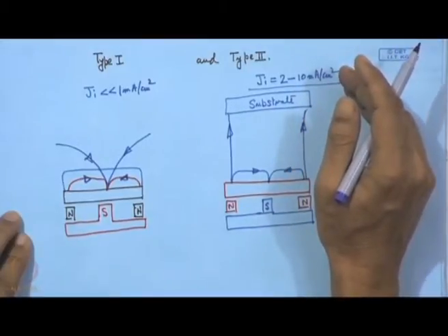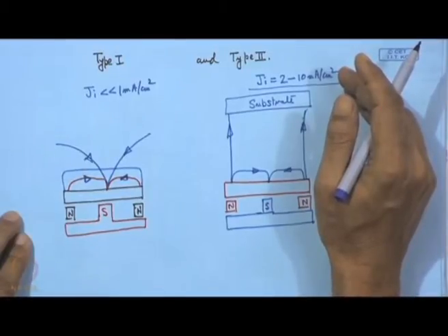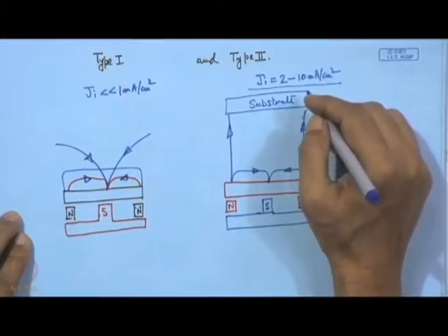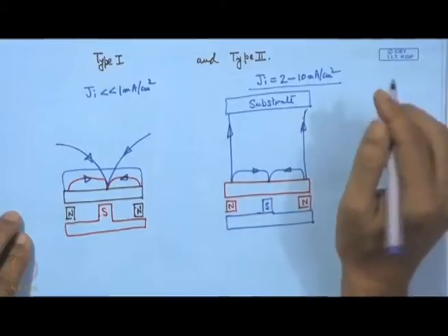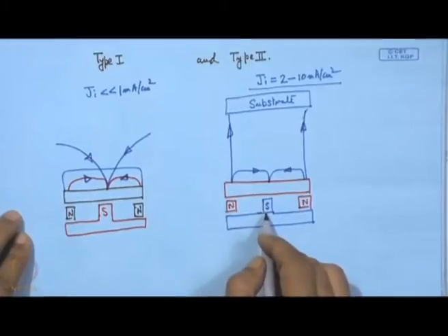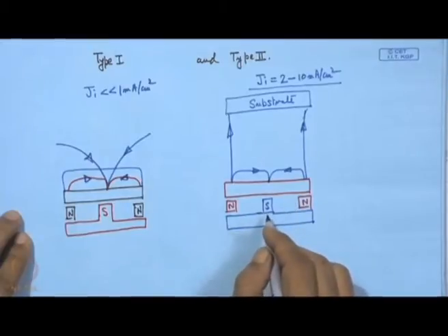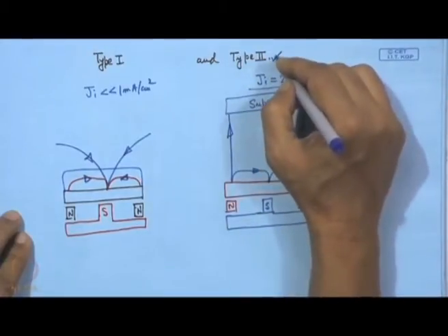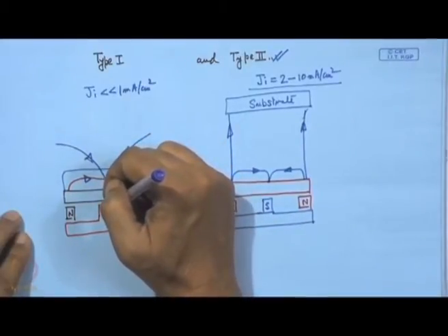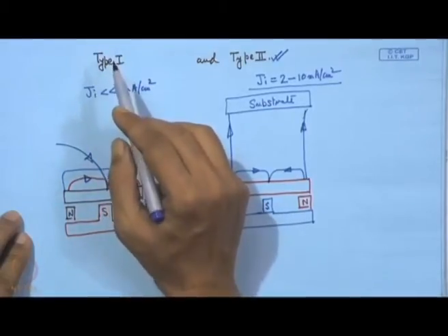So, low energy ions but with high flux density can be created just by stretching this plasma volume by this unbalancing of the magnet. In this case the ring magnet field strength is greater than that of the central magnet, and this is known as type 2, whereas where we have a stronger central pole, that is known as type 1.